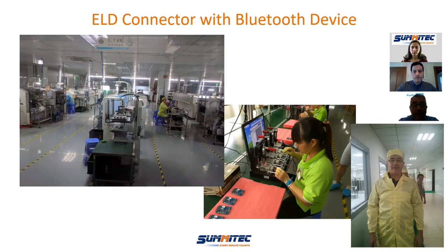So the LTE Cat-M has a lot of advantages. It's very reliable in terms of connectivity because it's a lower rate. So you're not going to watch a Netflix movie on the Cat-M modem, but it's extremely reliable to send short packets as needed by telematics. And also all the operators have implemented LTE Cat-M in the lower frequencies of their spectrum, which again makes it a long range, high reliability product.